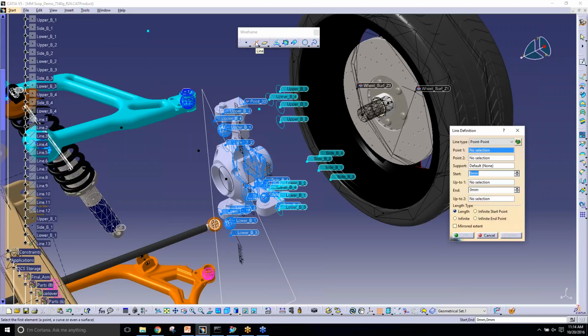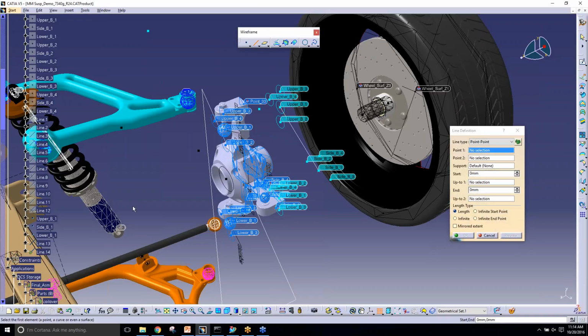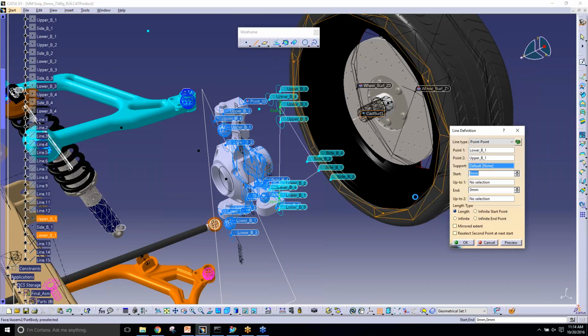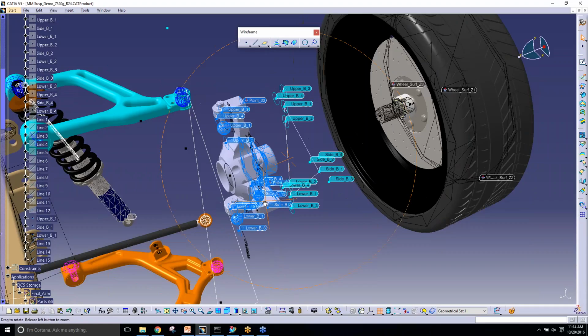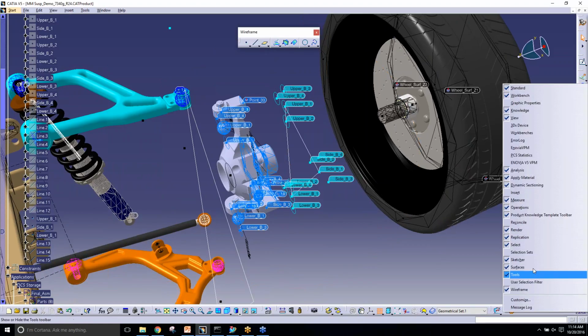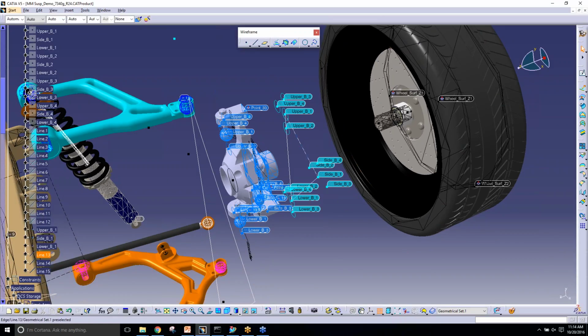You go right to the point, or line to line, create the upper B, side B, side B to the lower, oops, and then lower to upper. There's my triangle. There's a wireframe that I can specify or want to show in 3DCS. Turn this on. I'm going to change the color. I'm going to change the thickness so I can see it.